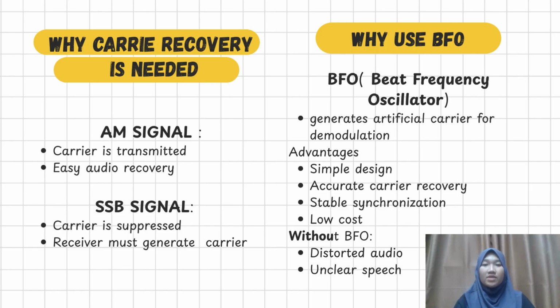Next, we go to why carrier recovery is needed and why we use BFO. Carrier recovery is needed because for an AM signal, the carrier is transmitted and audio recovery is easy. For an SSB signal, the carrier is suppressed, so the receiver must generate the carrier. Why use BFO? BFO is the beat frequency oscillator. The function is to generate an artificial carrier for demodulation. The advantages are simple design, accurate carrier recovery, stable synchronization, and low cost. Without BFO, the audio is distorted and speech is unclear.